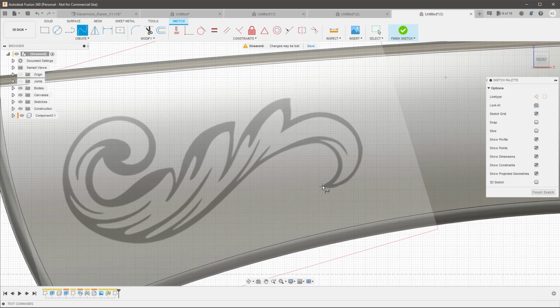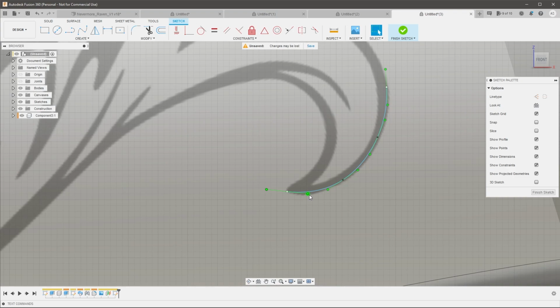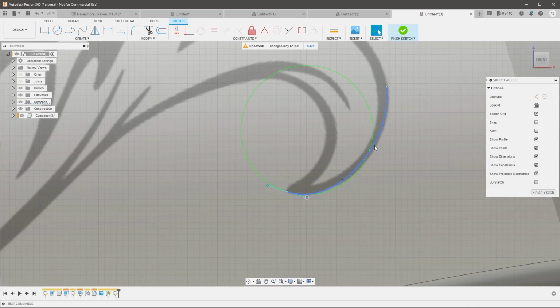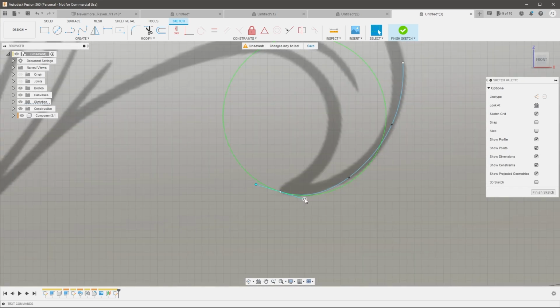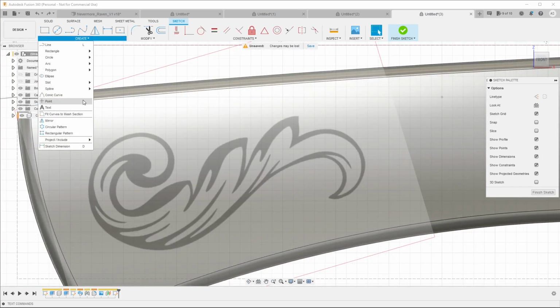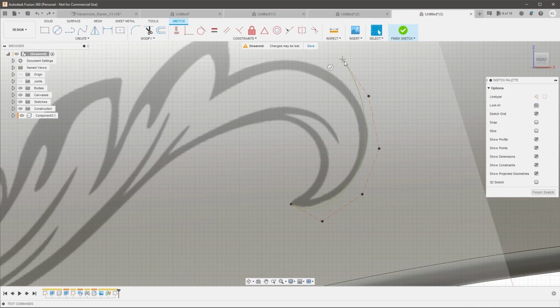So if I go fit point spline and I draw it, we can stop here. You'll notice though that now I have to come back in and adjust these, and these knots that are in the line are straight in line with the spline. And so if I drag this out, you'll notice that it's bending the other one back in. Whereas a control point spline, where that kind of differs, is the knots aren't in line with the spline itself. They sit outside of it. And so I can then draw basically around the shape like that.